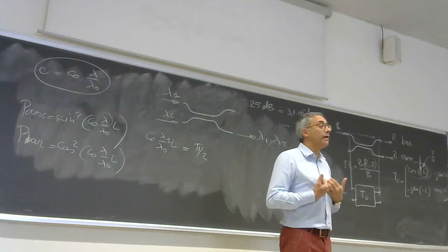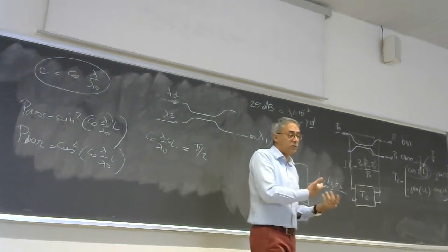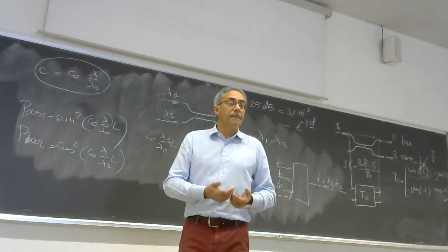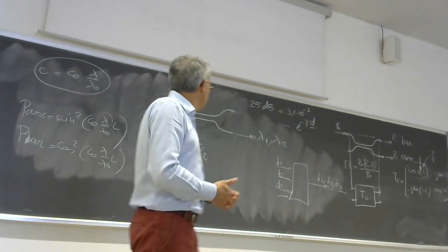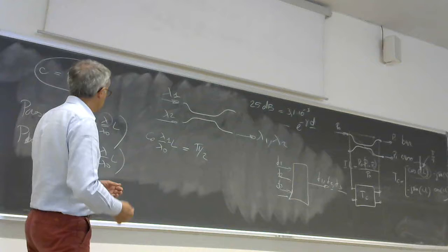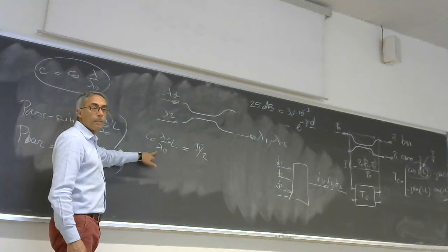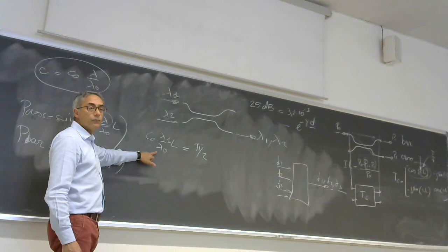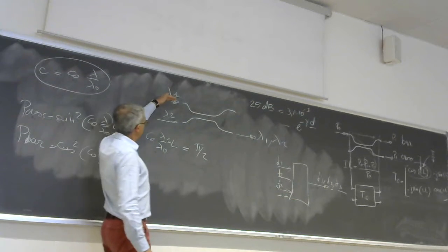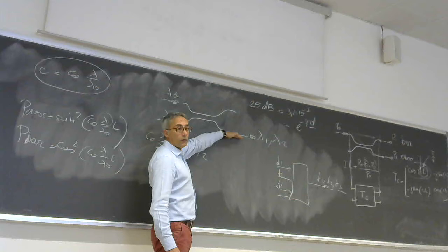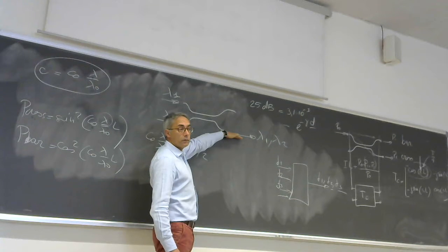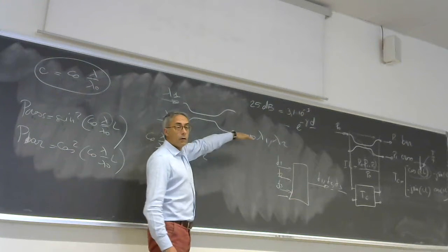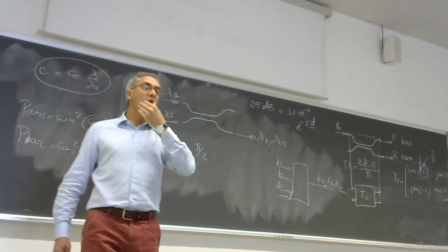When I say multiplexer, I mean a wavelength multiplexer or frequency multiplexer. Just on the formula, on lambda 1, we are imposing the half pi because we want lambda 1 to go on the cross. Yes. But in this way, we don't change even lambda 2 that goes.